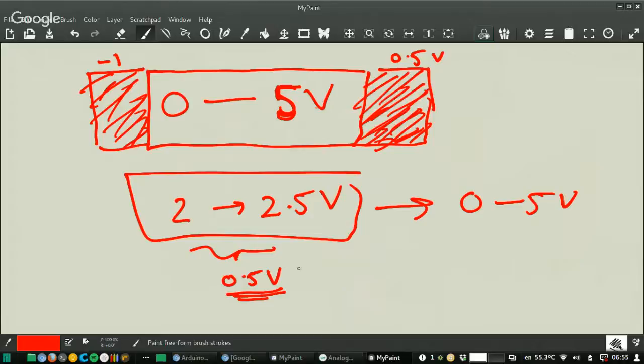You can use this and have 10 times less resolution, or inside the datasheet there is usually a small electronic diagram on how to convert this into a bigger range, so you can read it with better resolution. Usually all of this is in the datasheet, but let's see case by case.